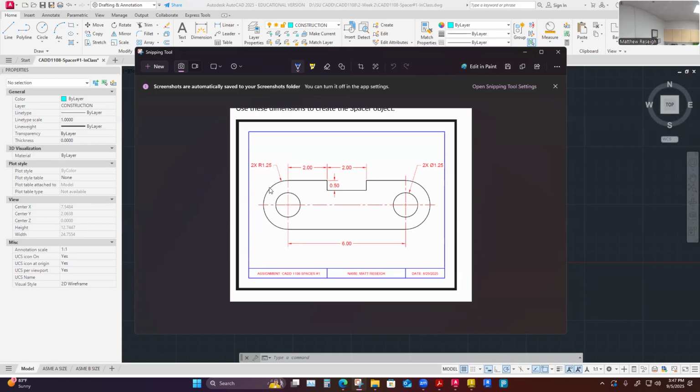So how I interpret that is I need two of these that have a radius of 1.25. Essentially, from the center out to that edge is 1.25 in both directions. So I need to double that to know what the diameter across this is. And that diameter across this will be the width of this piece. Let me add this in my head. It's going to be 2.5 inches. So this thing is actually 2.5 inches. I did have to do some math. When I created this assignment, I did make someone have to do some math to figure out the overall width. 2.5.